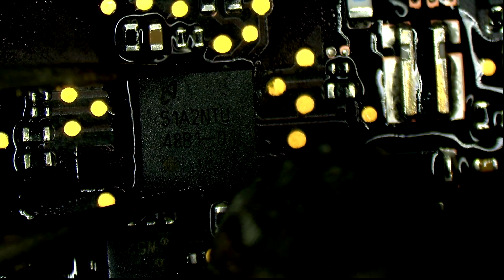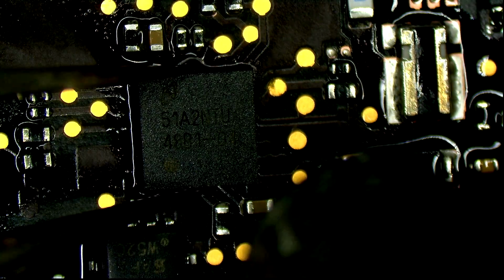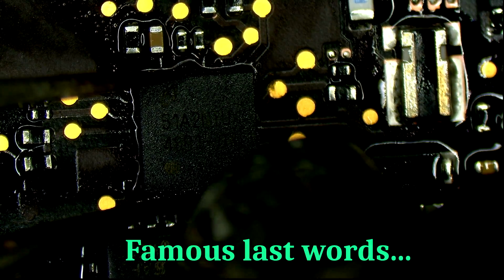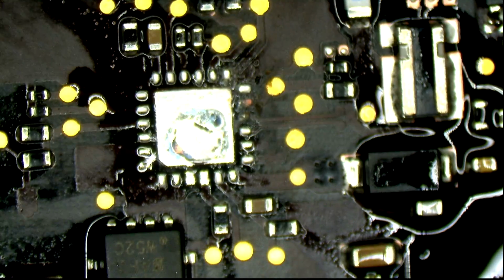Say goodbye, corroded backlight chip. It very rarely, if ever, is the actual backlight chip. So you'll see, once I replace this, it's probably going to wind up being something else like the screen. But we'll see. Actually, never mind, I take that back. Okay, so let's see. We've got something that's pretty corroded here. It's almost never the backlight driver on Retinas. You guys have noticed, it's always the LCD connector or something like that. It's never the LED driver. So this is a rare case.